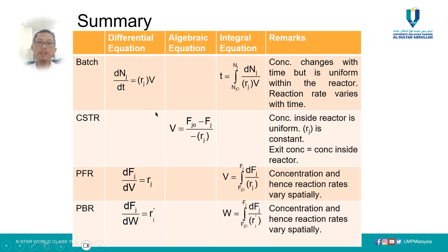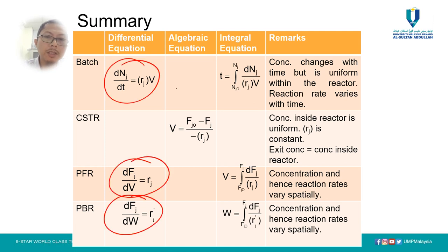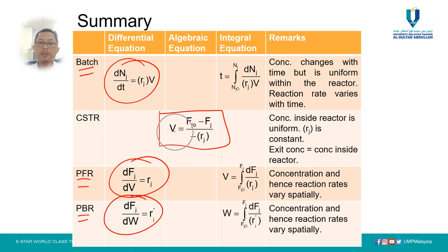In summary, these are the equations involved in reactor mole balance. As you can see here, there are three ODEs or differential equations for the batch reactor, PFR and PBR. On the other hand, you will have a simple, straightforward algebraic equation to determine the design variable of the CSTR, which is volume.